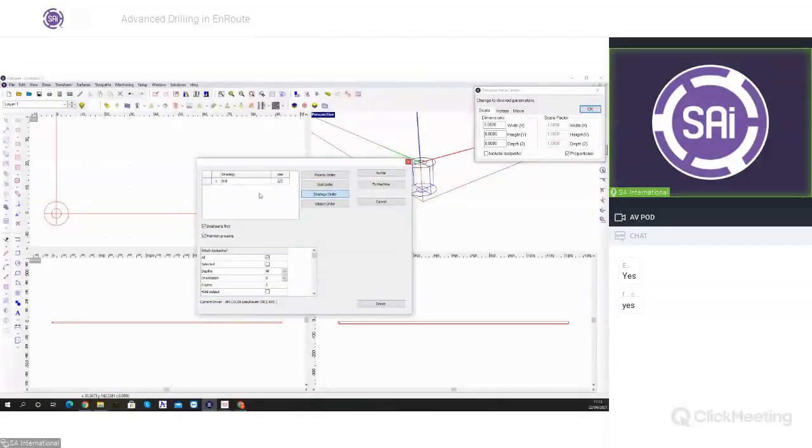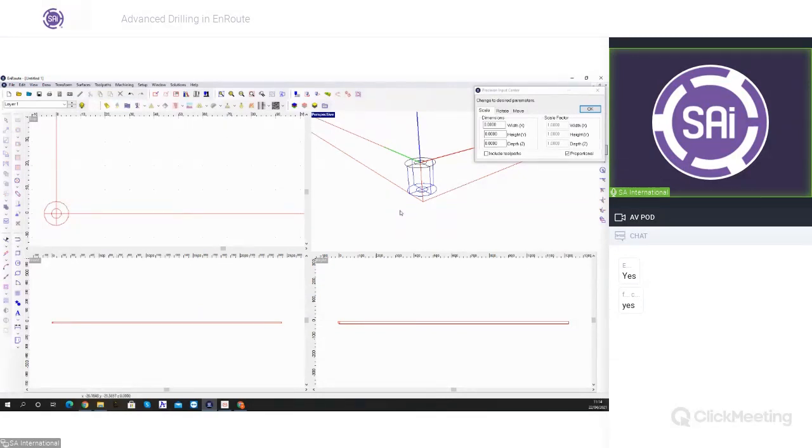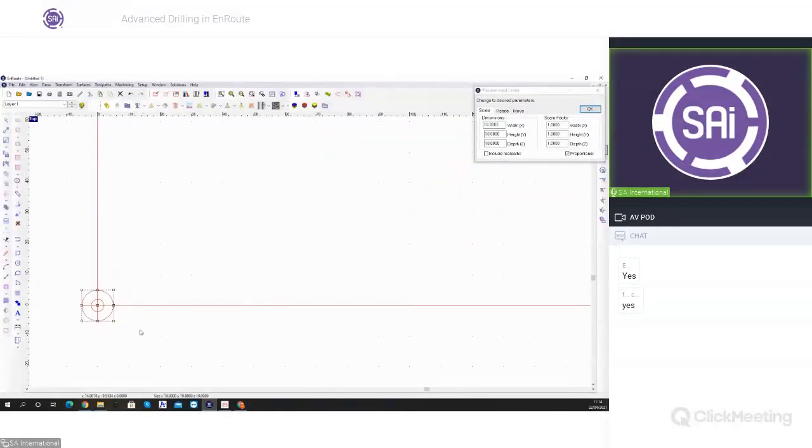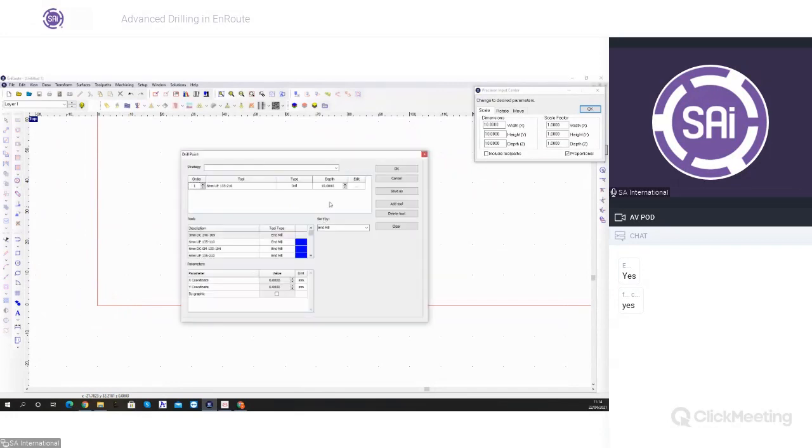So in most cases, you'll first want to do all of your drills and then continue with your other strategies. And this would let you keep these holes as drills instead of having to deal with them as routing offsets. So for ordering, that will make it easier. And let me just delete this one again and move back to the standard drills.